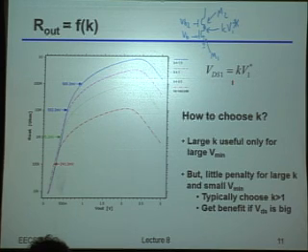And the reason is the following. If you look at this plot, literally all I did was move this bias point around, either by changing this bias voltage or by changing the size of that cascode transistor. What you'll notice is that below a certain voltage, they all give you about the same output impedance. They're all comparable. There's not really much of a difference.